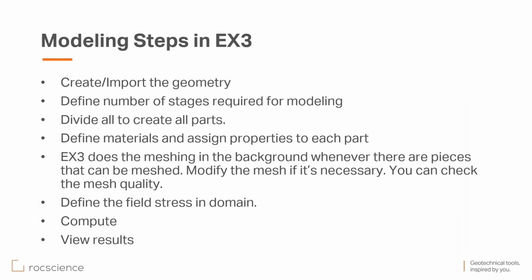Moving on, I'm going to be talking about exactly how you build a model in EX3. So the first step is to actually build the geometry. You can create this from component pieces or import geometry and repair it and post-process it directly in the program. Once you have your geometry built and it's something you're happy with, you can define the number of stages required for modeling. So this can be mining steps, for example, for how you're going to do your excavations.